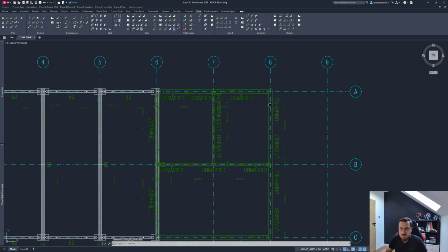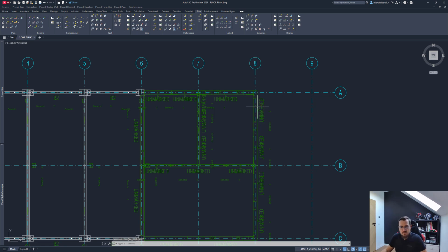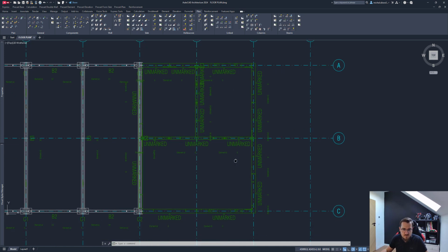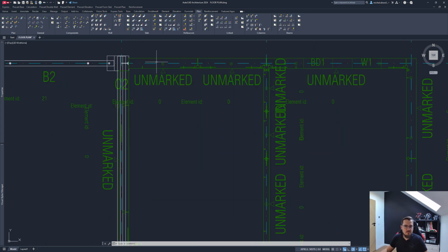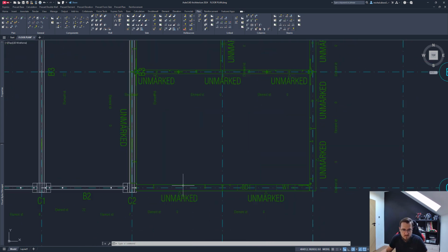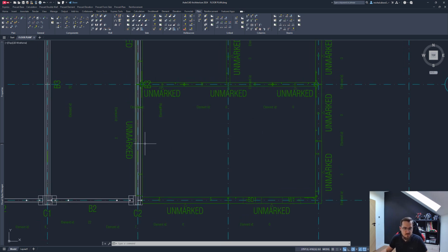That's done, really. What I now want to do is show you the panel thickening, because I want to place some slabs and I want to place them on some panel thickenings. So let's do that. Maybe in this section here. Now too many walls. So let's maybe do that here. Okay. So what I'll do here is I want to create a panel thickening. So I'll just click on this. Sorry, not this one. Draw panel, click thickening, and I will select an element, right?